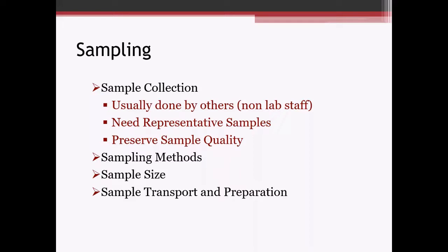So for example, for a particle size analysis, the minimum sample size per that test method ranges from about 1 pound of material for 3/8 size material up to over 11 pounds for gravel particles up to 3 inches. And materials can't be reused between the different test methods, so something that needs to be considered is how many tests are going to be run during the testing phase.